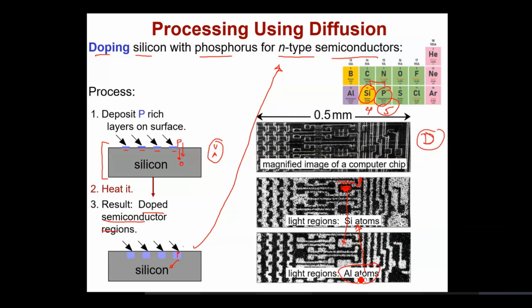So you have used aluminum because it has high electrical conductivity. There are other elements which also have high electrical conductivity, such as copper, gold and silver. But the reason for using aluminum here as an electrically conductive path is its very low diffusion coefficient in silicon, which makes it difficult for aluminum to diffuse into silicon, making it a stable connection. What is diffusion coefficient? We'll look into it in a few minutes.